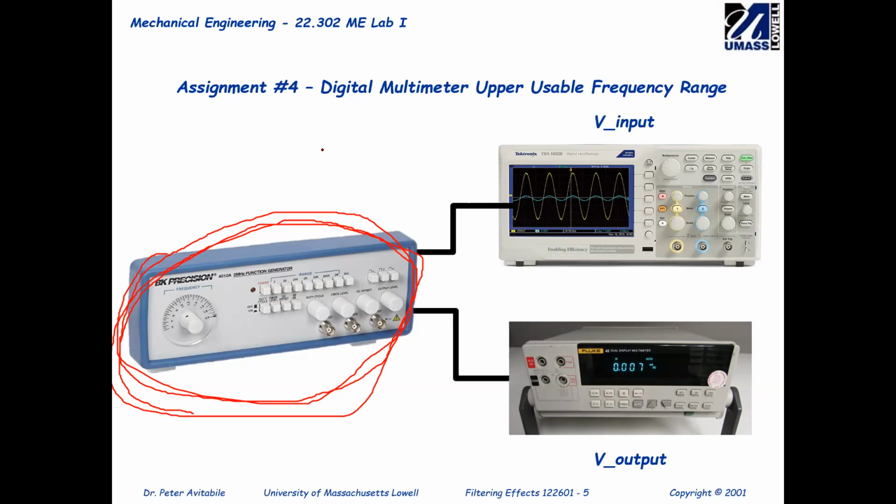So I'm gonna continue. I just want to read out loud the equation that we have there. So gain dB, or gain decibels, is equal to 20 log base 10 of the gain. And that gain is just the ratio between the output voltage and the input voltage, okay? Right now in this experiment, we're just gonna quantify output and input. So I'm gonna start with step number 1.